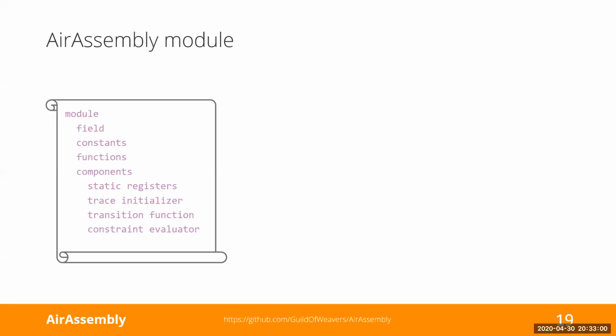If you do that, is there some inefficiency involved from the fact that you're not using all of the registers in all of the modules? So you presumably have to choose the number of registers to be the maximum number needed by any module. Yeah, there are different techniques to optimize for that, and that's going into very complex territory. But yes, there are inefficiencies, and they don't necessarily come from the number of registers.